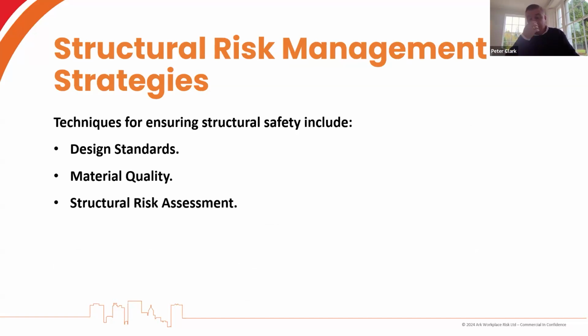Routine inspections are crucial. That structural risk assessment, at least once a year, you're looking at the structure of that building and you're looking at the condition of the building. Load capacity of structures, particularly for renovations, particularly if something changes in the usage of the building: you should be conducting load assessments so that they can safely support the new intended load.